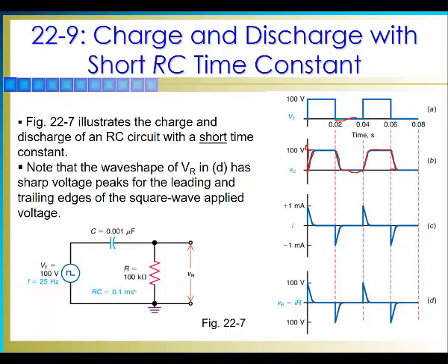Now what about the current on the circuit? When the capacitor is discharged, there is no charge. We apply the voltage, so the current will be fully running through the circuit. It will start right there. But as the capacitor starts charging, it starts blocking the current until it's fully charged, and then the current stops, because remember, when capacitors are fully charged, they behave like an open circuit.